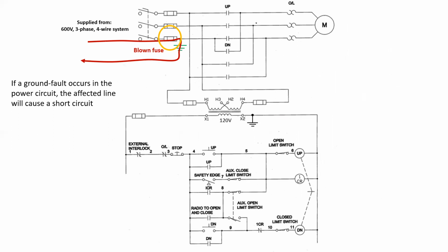Keep in mind that if this was a breaker setup with a 3-pole breaker for 3-phase application, all 3 of the lines would trip simultaneously. In a fusible disconnect, only the fuse that has a short circuit will open, and in this situation, the motor would then be running single phasing, so higher current and overloaded.